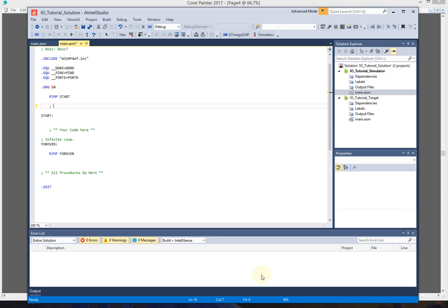So for our demonstration, let's configure port E. So I go to start code here. Remember, never forget, first order of business, configure all I/O ports. Let's start with port E. I want to configure port E all inputs because I want to read all the dip switches. So I'm going to say LDI R16, 0. And then output, do you remember what register? I would say pin E.